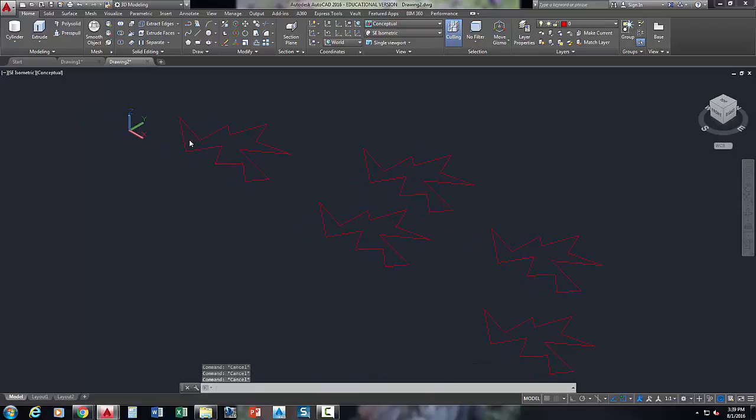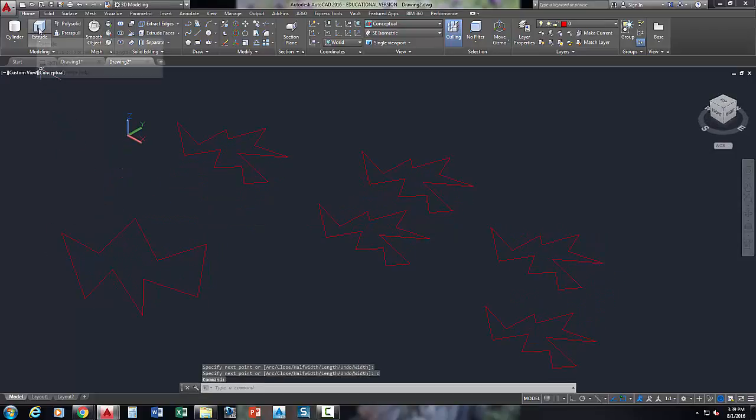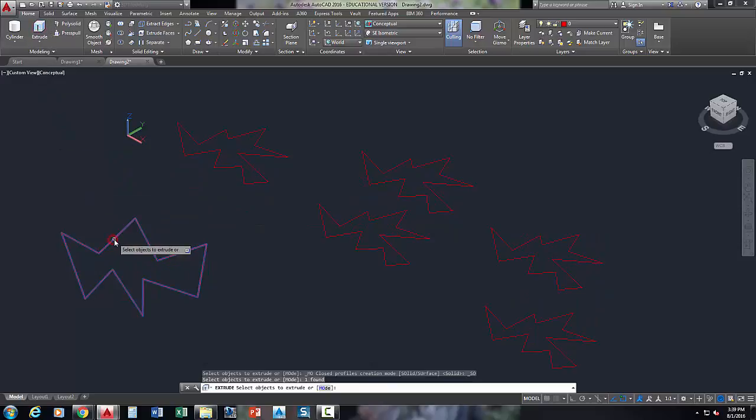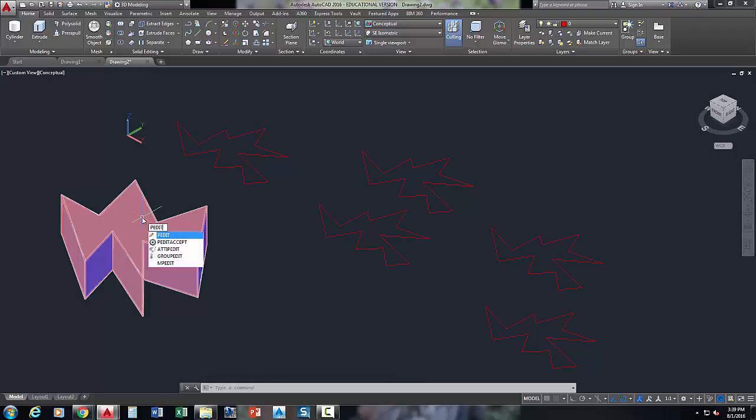What we had to do before is use a polyline. And so you could have started with a polyline, assuming that polyline is perfectly flat. And you could extrude, select the polyline, and that's more what we were looking for it to do. So if you have regular lines, there's a couple of things that you could do. In AutoCAD, it used to be the p-edit command, polyline edit.